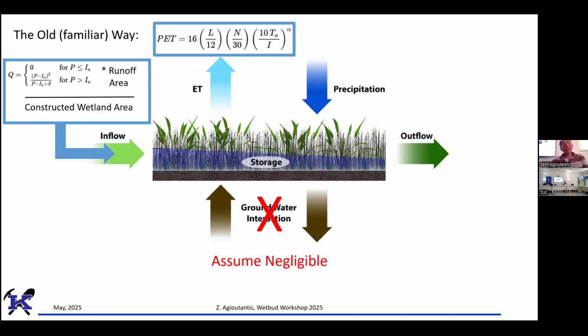There's multiple formulas to calculate ET. This is the Thornthwaite equation, which does a monthly ET estimation. It's an estimation. We estimate that in July of this year, in that area, we will have so much water lost due to evapotranspiration.